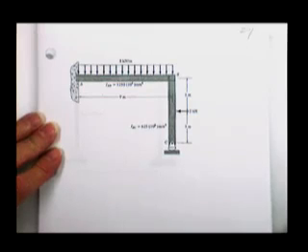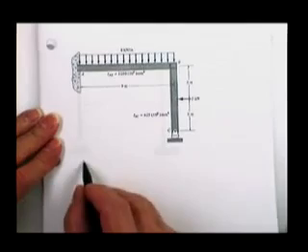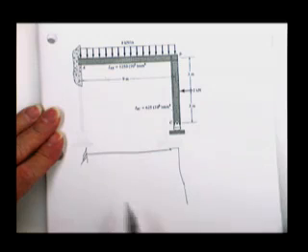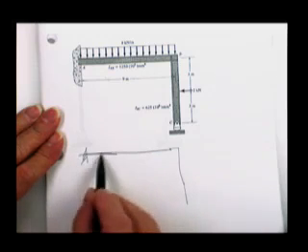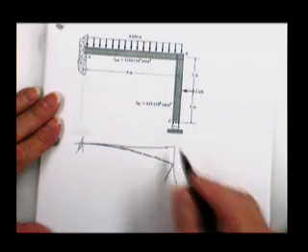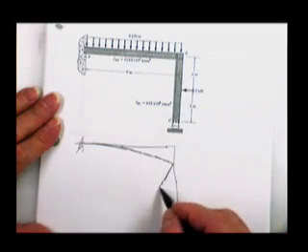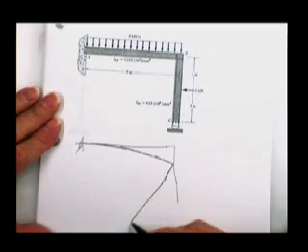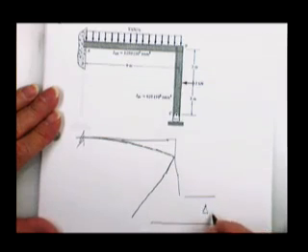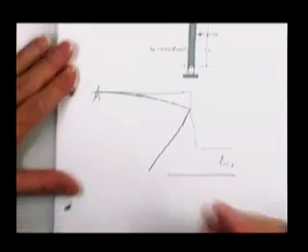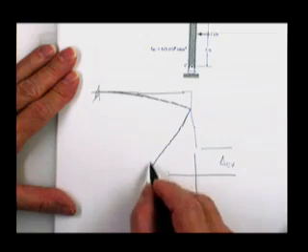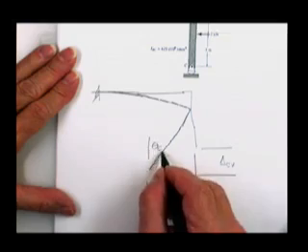I don't think that one looks that much different from most of the rest of them. The most obvious primary structure would probably be this. It would bend down. It would stay, oops, it's got a force on here too. It would bend in. You would have a delta at C vertical. You would have a delta at C horizontal, and you would have a theta at C.